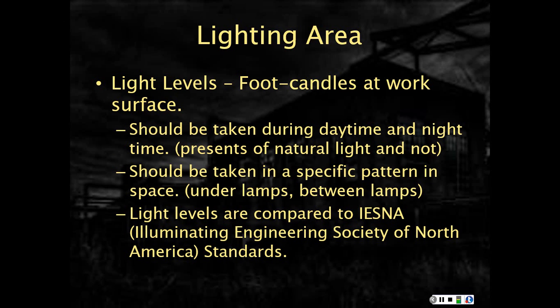And then finally, we need light levels or foot candles at the work surface. Now, it should be taken at least twice. There should be a daylight reading and there should be a nighttime reading. In other words, we're taking it during the daytime where we can take into consideration natural light, and then again at night to make sure that lighting levels are still appropriate when we don't have access to natural light.